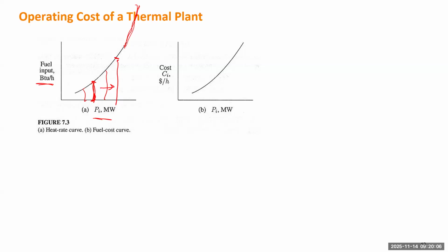So usually we consider a certain region of the power output, from some minimal output to the maximum output, and we model this part of the fuel input function. This is just the volume or mass of the fuel. If you price this fuel, you will have another unit, which is how many dollars you are going to spend to generate this power.